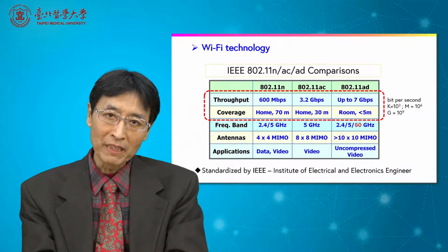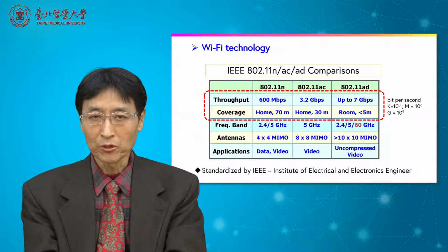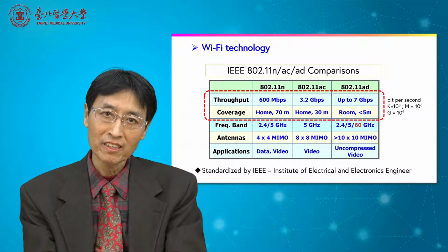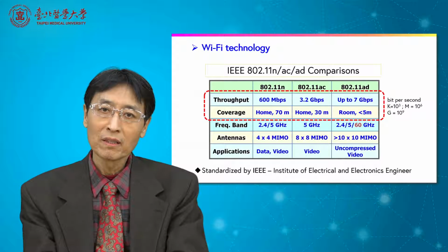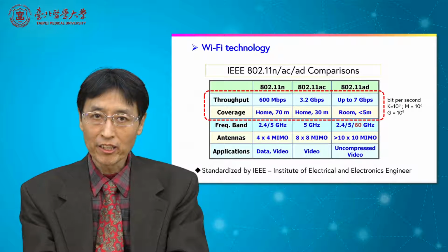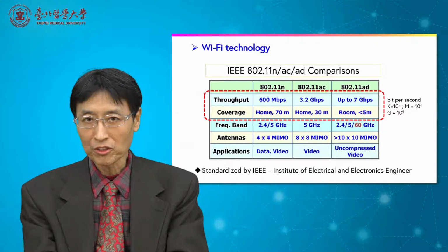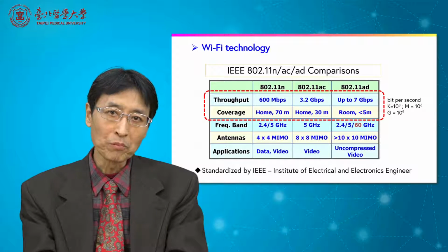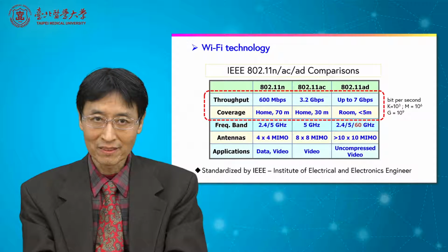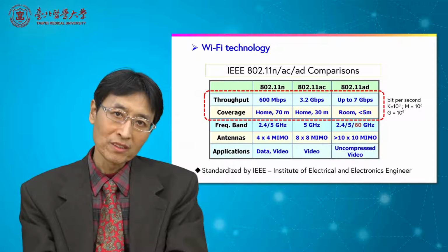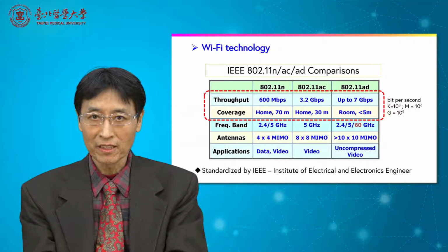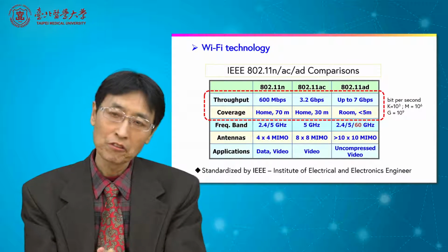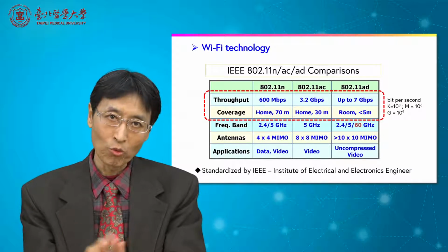The coverage will be basically less than 100 meters. Of course, it depends on the strength of the emitted signal, the transmission power, which can be adjusted. It also depends on the environment, since furniture or walls will block the wireless signal a lot. So the coverage or distance of the wireless signal is basically a reference. 100 meters is basically a theoretical value for your reference. Okay, this is Wi-Fi technology.